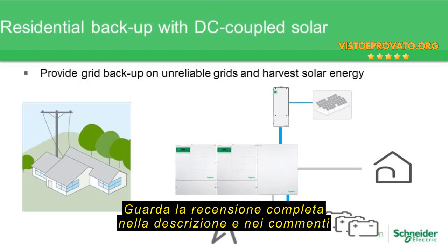Just because you have an event, event being like a big storm or something like that, doesn't necessarily mean that you're going to lose power, but you should be aware of those large loads. Even at 50 amps, you think about what 50 amps is kilowatt wise, that's a very, very large system. So at 230 volts, 50 amps, we're talking about over 12 kW.